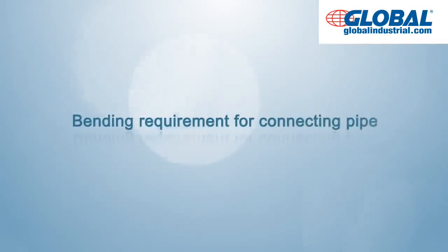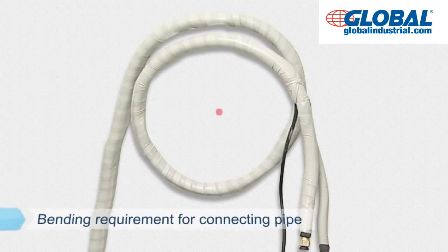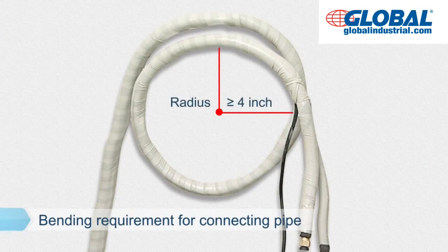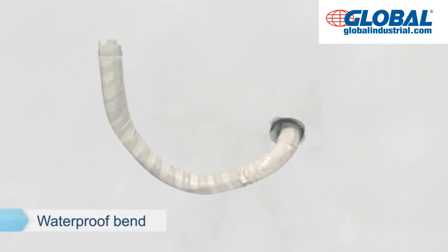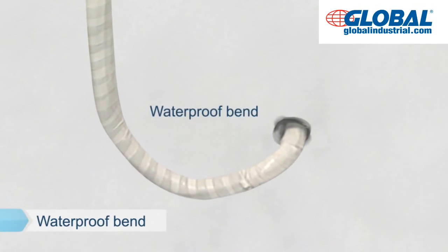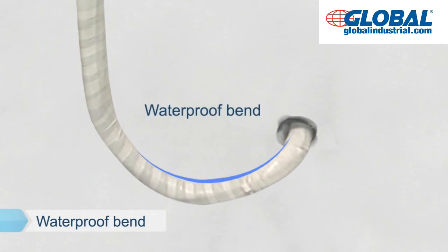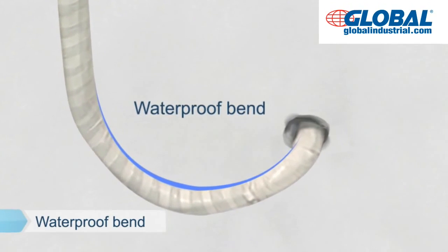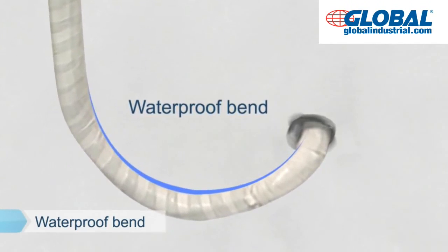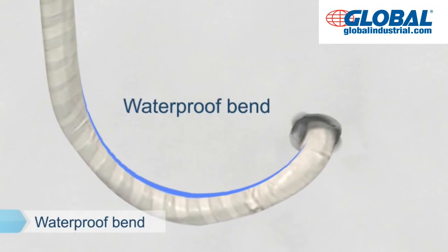Bending requirement for connecting pipe. Bending radius of connecting pipe should be more than 4 inches, and connecting pipe shall not be squashed during bending. When exit hole of connecting pipe is located lower than indoor unit, a section of waterproof bend downwards is required for exit hole of connecting pipe to prevent rainwater from pouring into the interior.